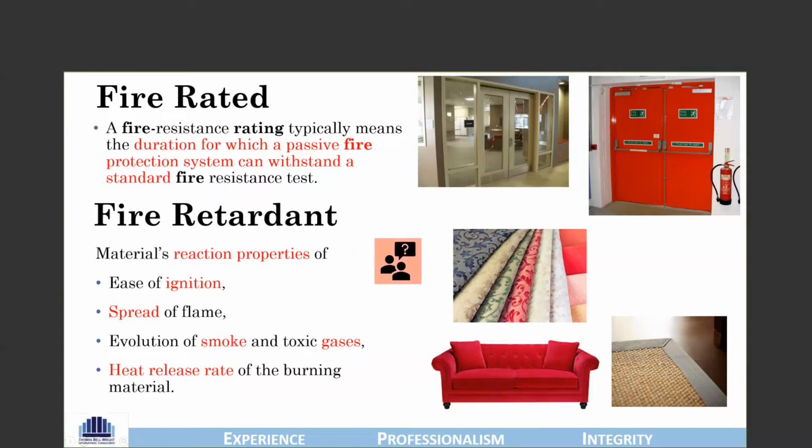But if this material is lying next to a table, which has a very high ignition temperature, but also has a very high heat release or calorific value, which means the amount of energy inbuilt in that material is high, then it is good to imagine and understand that bringing such materials together could lead to a catastrophic situation where an initiation of fire caused by one could cause the fire to grow heavily onward.